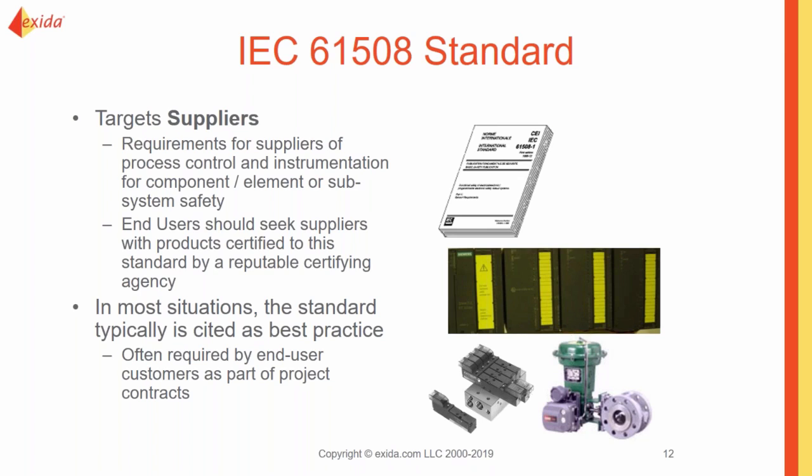However, if IEC 61508 is kind of ignored, brushed under the table, and an accident does happen, yes, it wasn't a law that you had to follow the standard. However, especially in civil cases, do you want to be asking or answering the question, other engineers were using the standard, everybody kind of knows this as best engineering practices, why didn't you? So it could be a costly mistake as well.